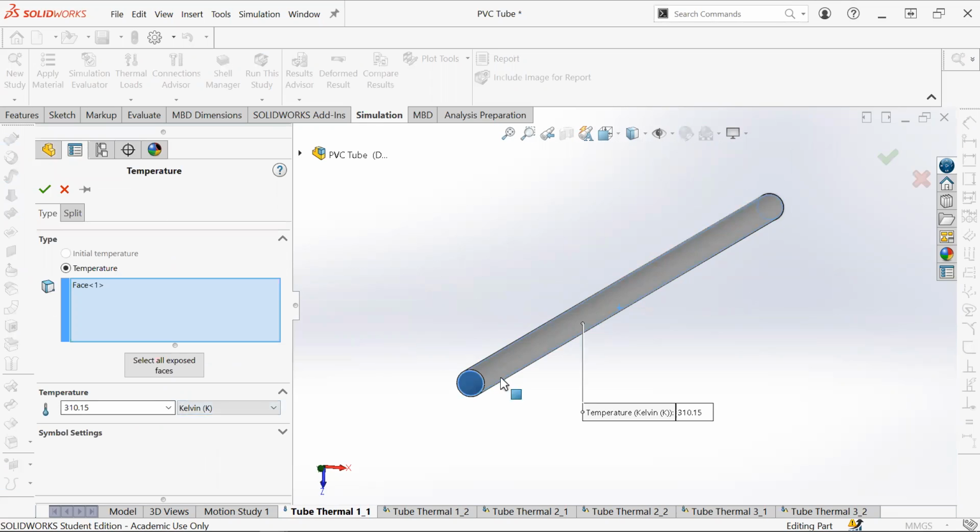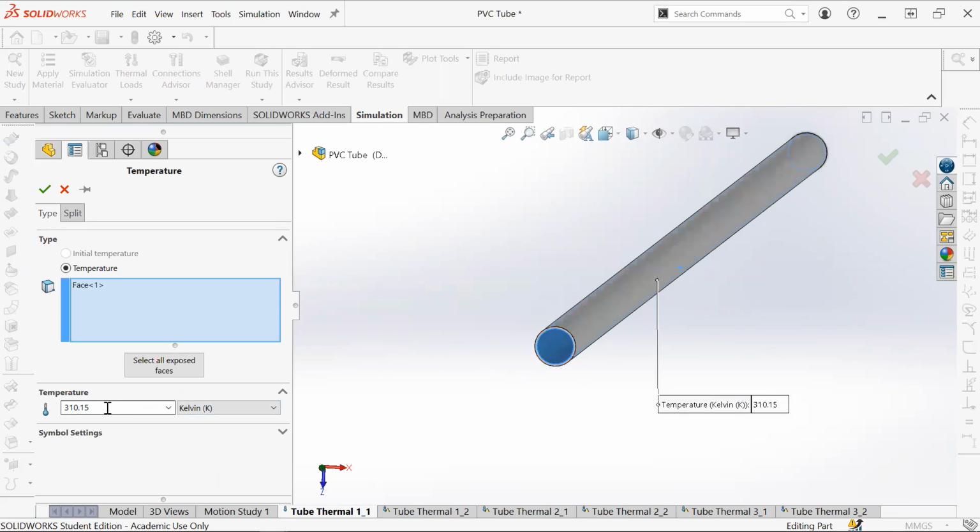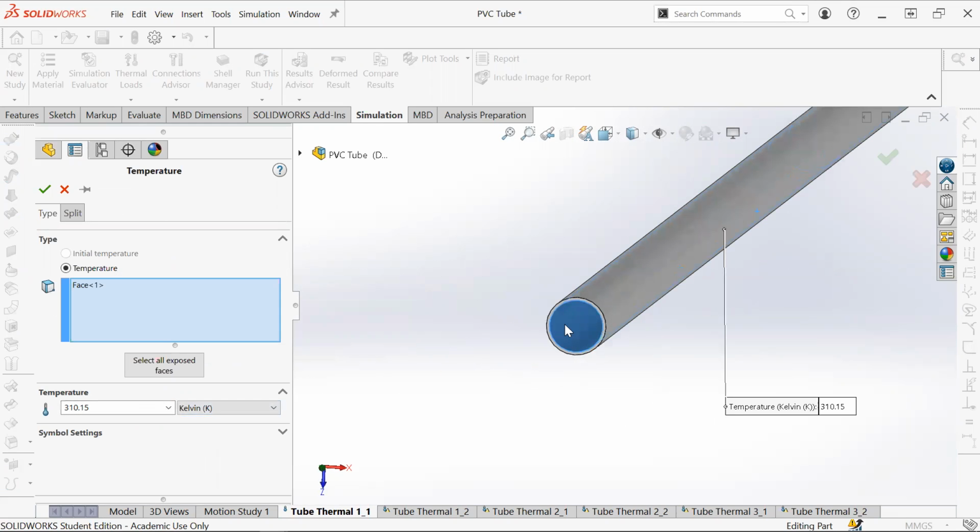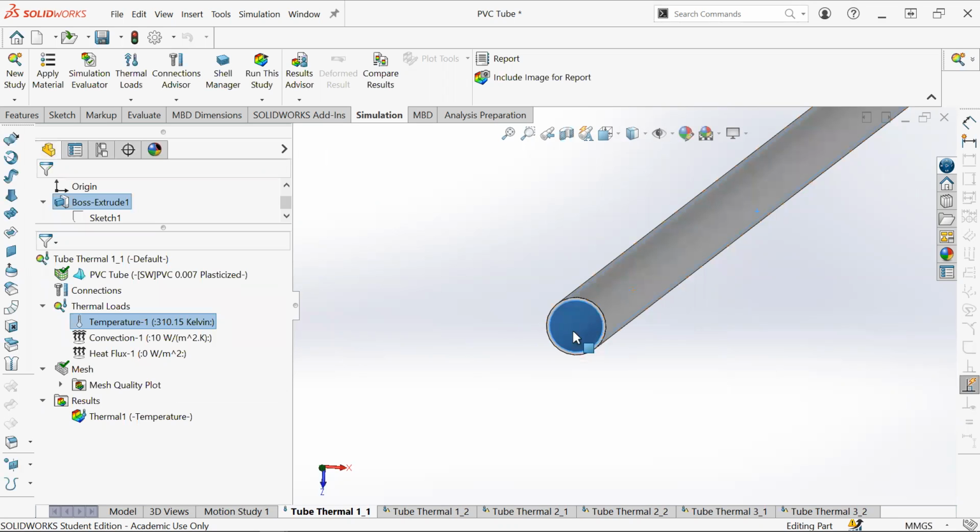Here, I'm setting the inside temperature to roughly 310 Kelvin, and that's simulating blood filling up this tube. Essentially I'm assuming to start that the temperature on the inside and the outside surface are the same temperature as the fluid flowing inside of the tube, so roughly 310 degrees Kelvin. So inside is 310, and the outside to start with is also 310. And then for convection here,